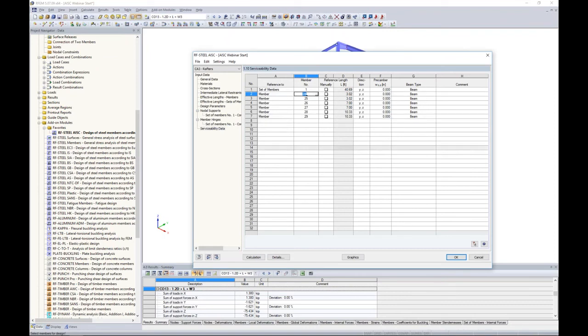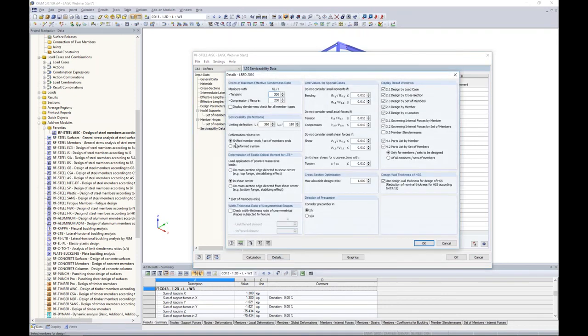All of those members are populated here, but this time I want to manually enter my lengths. I'm going to put in the full member lengths, 40.69. I hit my down arrow key and the F8. F8 will automatically populate those. The last thing that I need to do is to go into my details and change this to my undeformed system.